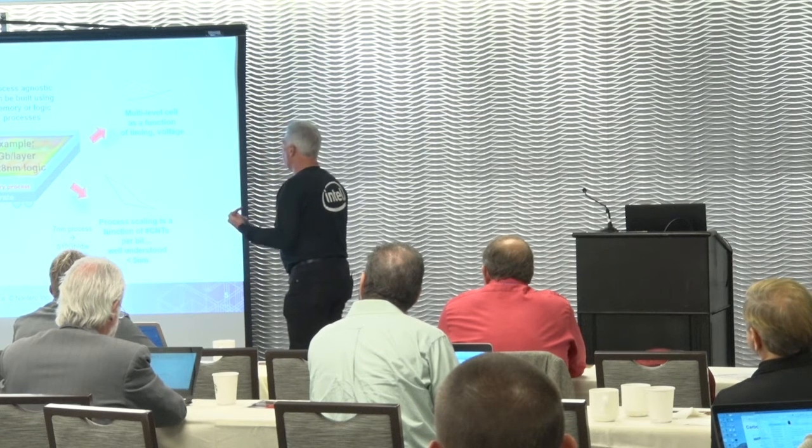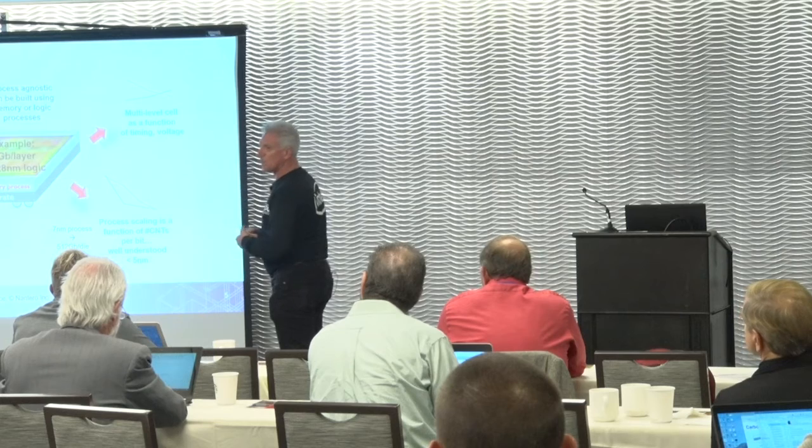So what are the things that we can do? Well, at 28 nanometers, we're fitting 4 gigabits of carbon nanotube cells in 100 square millimeters of die space. You can do the math yourself pretty quickly to figure out what you could do with that. But also, this can be taken 3-dimensionally.